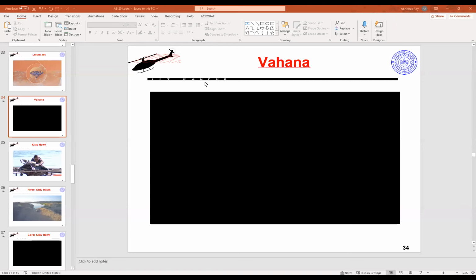When the flow is separated from the airfoil, what happens? What is there in that region between the airfoil and the flow? There is still flow, but the flow is no longer nice and laminar. If you remember the animations or other flow visualization videos I showed in the first lecture, and Professor Das also showed some of those, when the flow is nicely attached, it is nice and laminar. But once it separates, it will start to oscillate and fluctuate a lot. So there is flow. It's not like the flow has disappeared. The flow is still there, but it's no longer organized and smooth. It becomes chaotic. It becomes turbulent.